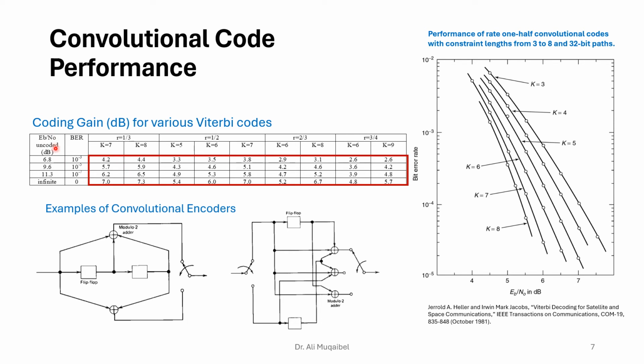Okay, this is the requirement for different probabilities of error. So the coding gain here is 6.5, 5.9, 4.4, and you can look at the numbers. This is like only requiring 1/4 of the power. Okay, so this is for rate 1/2. We have all the numbers. Those are the amounts of gain that you get. Of course, for 3/4 you expect the numbers to be lower in general.